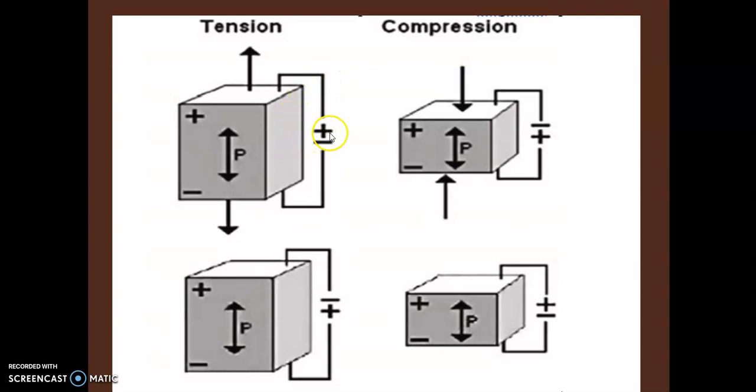And as you are applying positive charge to this plate, immediately negative charge will be coming here because what will happen? This positive plate will attract electrons. So negative charge will be here and on this negative plate, positive charge will be here. So that is also separation of charges. That is also production of polarization. But what is the reason? Reason is the applied electric field.